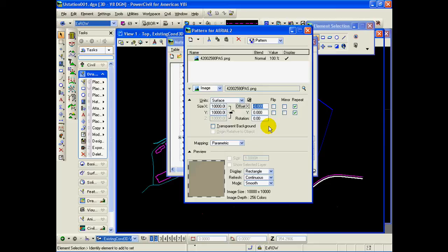If you're working with a raw image that you had to position over top of your design, you would use AccuSnap and get the X and Y coordinates. So I'm going to enter in those values that I saved, and in a second I'll enter the Y value.